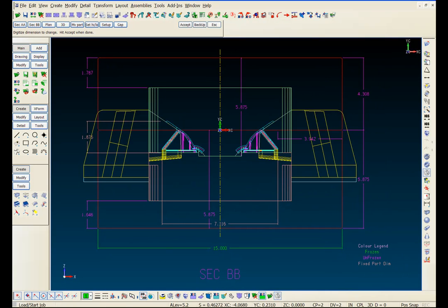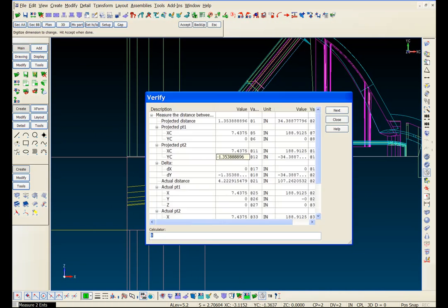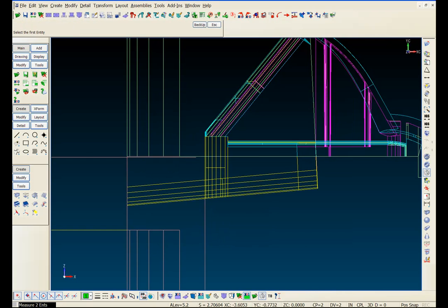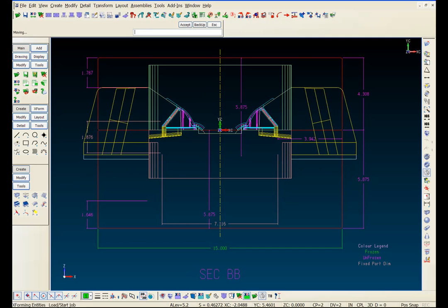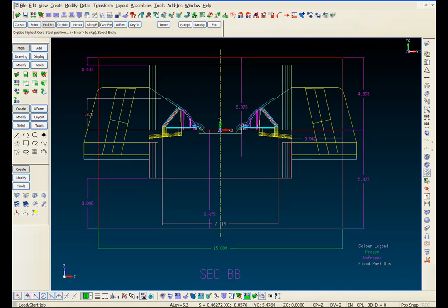So I have some modeled inserts and a modeled slide with my part here, and now I'm running it through the XMD Standard Moldbase Parameters dialog. So the first thing I'm doing here is just getting a height where I want to establish my 0, and I'm going to tweak my part, just moving the move part command. And now I'm going to go ahead and adjust my block sizes.